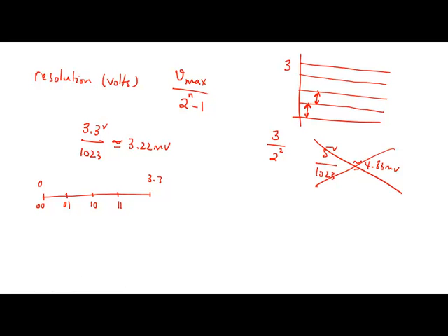Basically, if you look at your equations, the digital value that you want to get in terms of Vin is going to be Vin divided by Vmax, right? You want to know what is the ratio. If my signal is here, what ratio is it to this number?